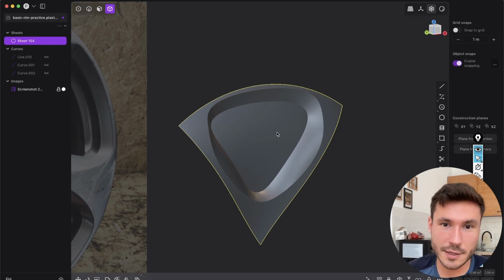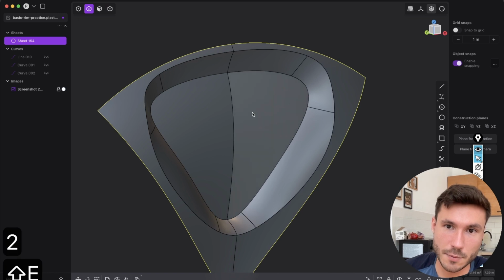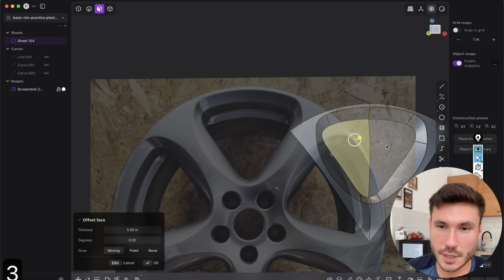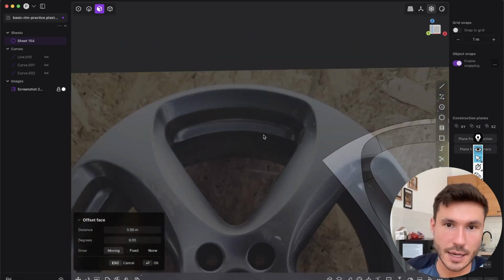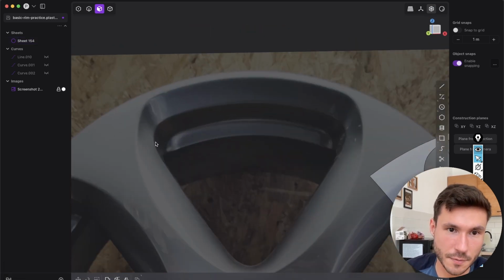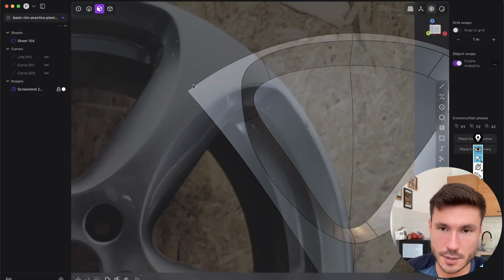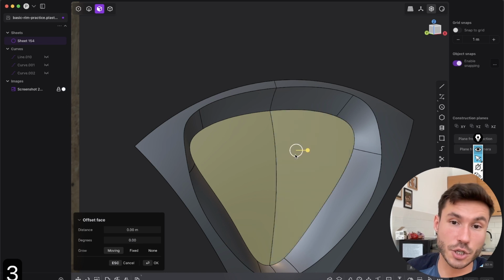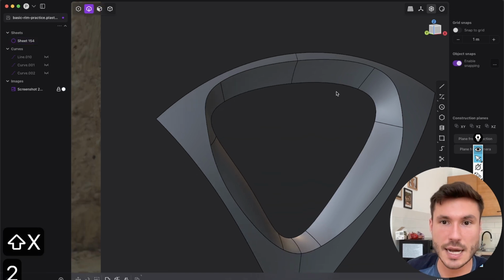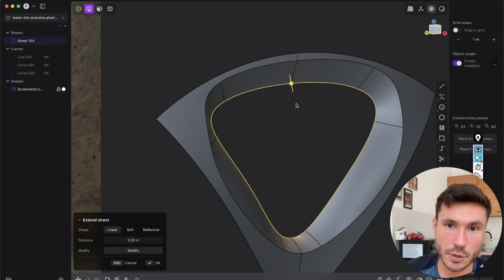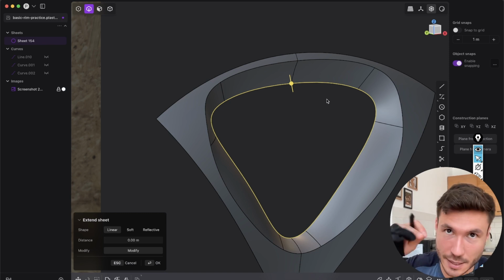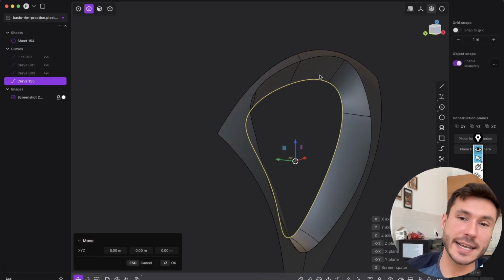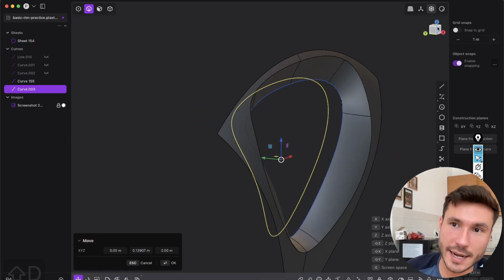But we still have some things to do, because we want, of course, to give it some fillets. And first of all, also let's delete that middle piece here, because you see it also goes a little bit inwards. So we can do that just very quickly. I will not explain every detail because we did this. So select just those faces and Shift X. And now Alt click in edge mode to get again the exact same shape of the curve. Shift D and Shift D again, because we will bring this a little bit inwards.